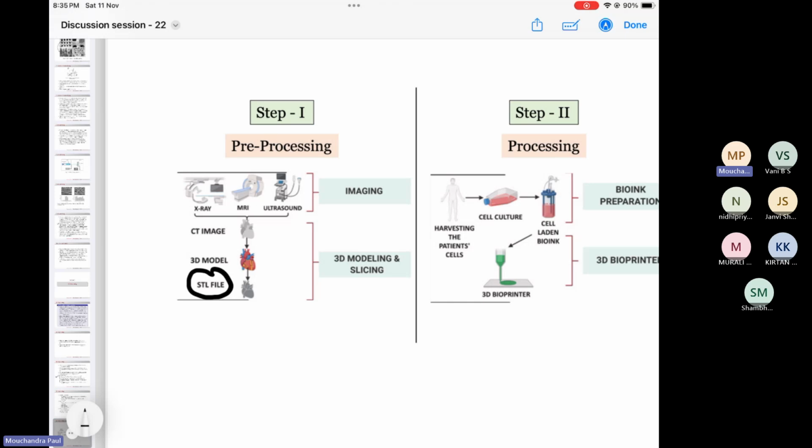It will start printing according to the 3D model that you have given, and you will get a model that looks like your CAD model. Also, don't expect that the obtained structure will look 100% like your 3D model, because the material that you are using is hydrogel, so the corners or the lines won't come out very sharp.